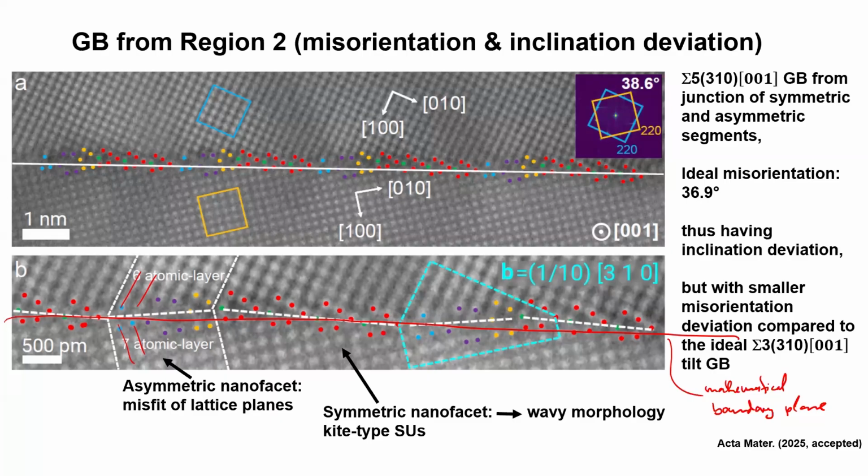So the Burgers vector of this secondary grain boundary dislocation will be a Burgers vector which doesn't fit to any of the two lattices. This dislocation-based description of grain boundary structures is exactly equivalent to the structural units description. You can either say there is a new motif, a new structural unit introduced, or you could say there is a secondary grain boundary dislocation introduced. The meaning is exactly the same.